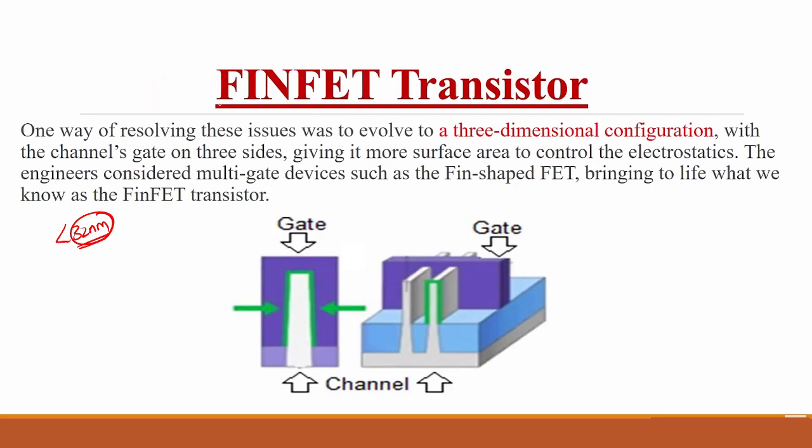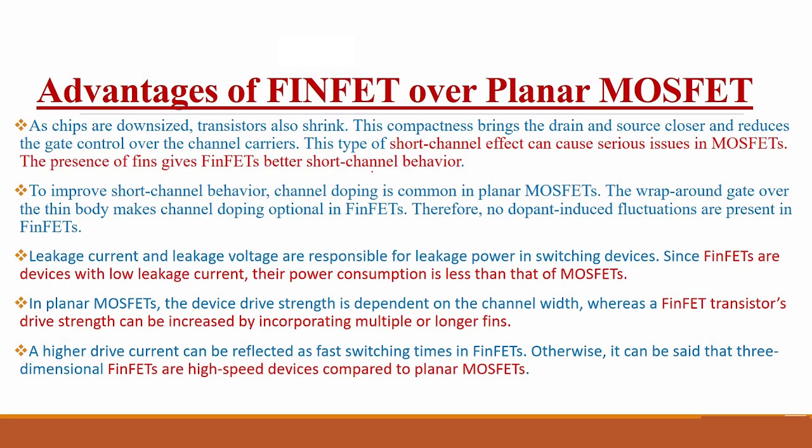FinFET I told you. One way of resolving this issue is a three-dimensional configuration. FinFET is a three-dimensional configuration. I told you two gates are there, two channels will be there, with the channel gated on three sides. So engineers considered multi-gate devices such as the fin-shaped FET, known as the FinFET transistor. This FinFET can support up to, sorry, 22 nanometer only. Again some problems will come. These are the advantages of FinFET over planar MOSFET.